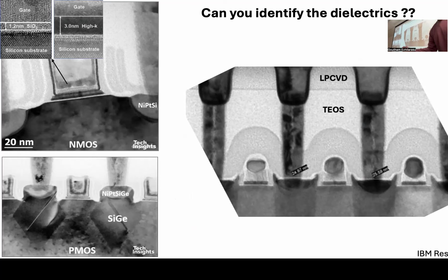No, we want the pores in this case because we want to lower the K. Oh, you mean the pores can sometimes occur naturally during the processing, but that is bad. That is a different thing, right? In this case, you intentionally introduce these uniformly distributed pores so that you lower the effective K.